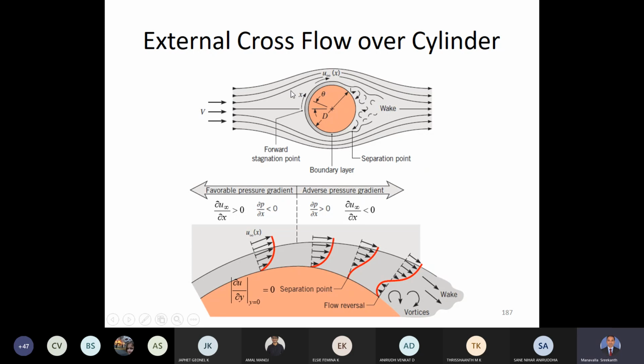So you see here, on the front side, the upstream side of the object, the flow layers are quite aligned with the surface of the object, but on the wake side, on the back side, the flow is not so aligned, and you see the small curved arrows. These are called eddies. This eddy formation takes place because of the flow separation, because now the flow is separating away from the curved surface so that it can catch up with the rest of the flow.